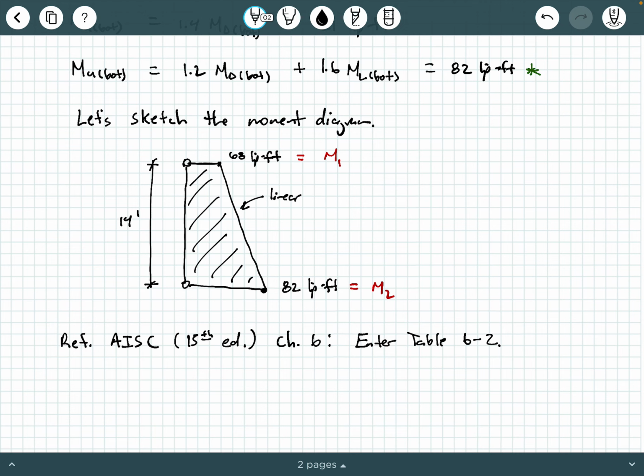And so if you look in that middle column of your Steel Manual, it says effective length Lc with respect to least radius of gyration or unbraced length with respect to x-x axis bending. So let's look at the right side of the table first, okay? The right side of the table will give us our phi b Mn values.